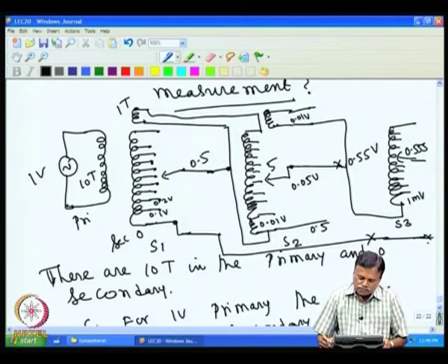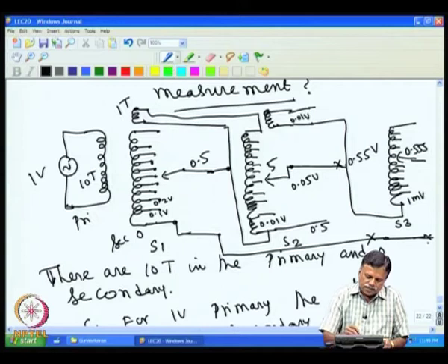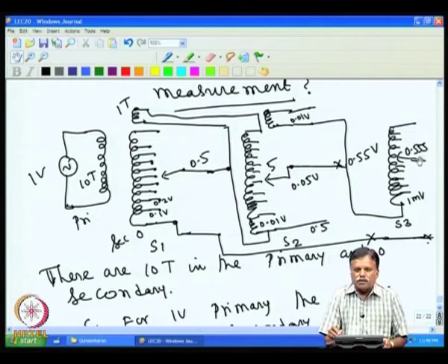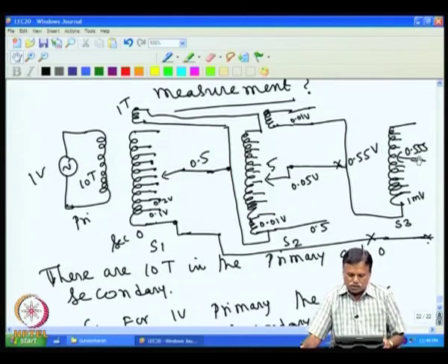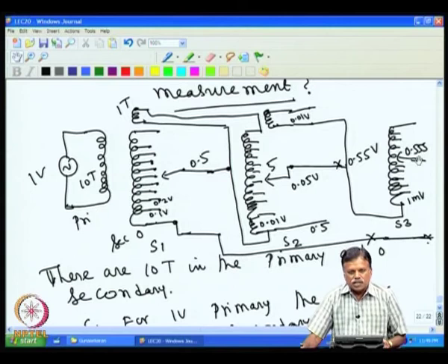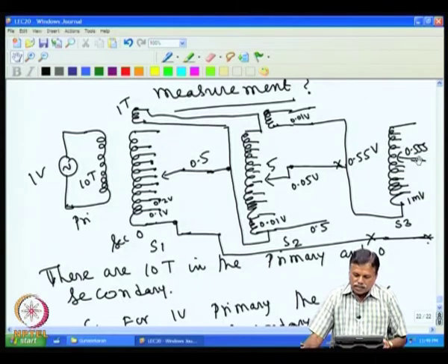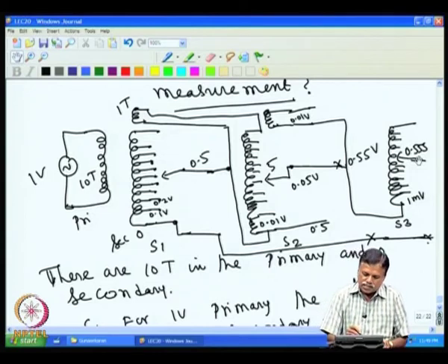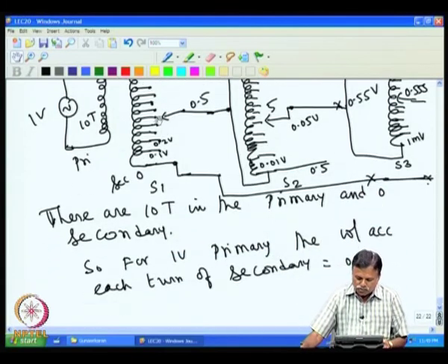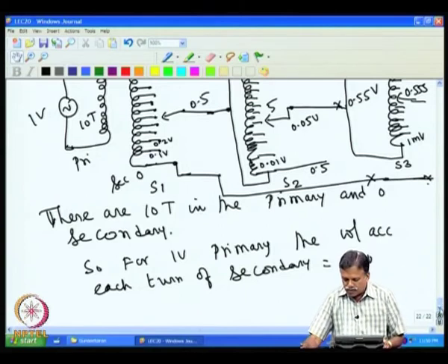So, by this arrangement, by varying the tapping, one can vary the voltage accurately, and there is no need to measure the voltage using a voltmeter, which avoids measurement error. If you look at this, this is how a commercial ratio transformer is made. This is a 3 decade ratio transformer, and in this case if you want to connect a resistance, one can connect from the top and bottom. So, I will put it in order now.